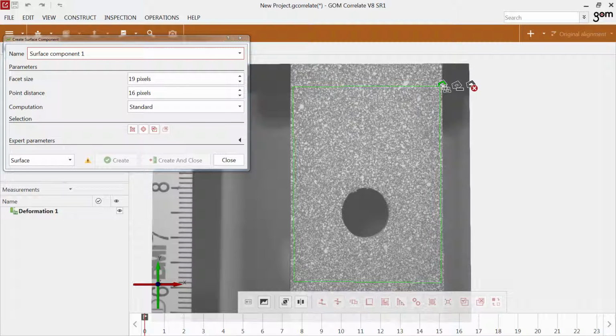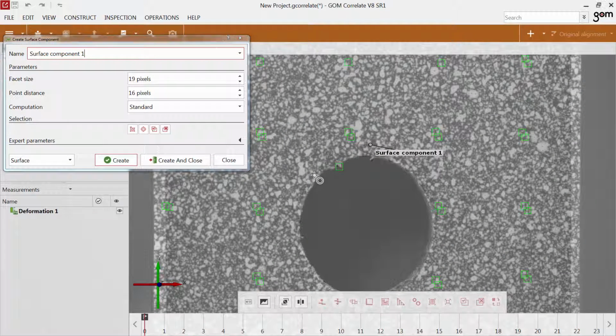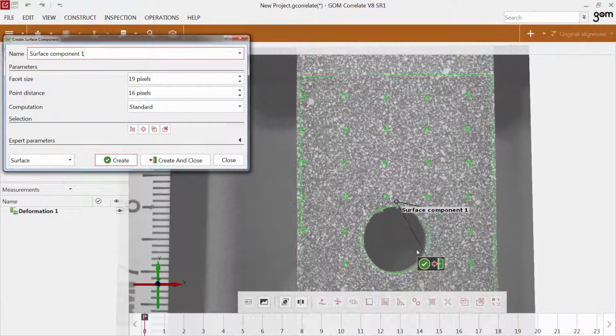Keep the right mouse button pressed and move it over the plus sign. If you now release the right mouse button, the software creates the selection. All data within the polygon is now selected and is computed automatically. To deselect the hole in the middle, click Select Deselect Circle. Again, finish the deselection with the right mouse button. Choose now minus for the deselection.